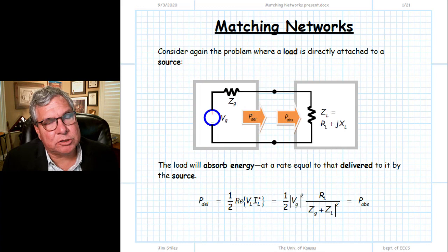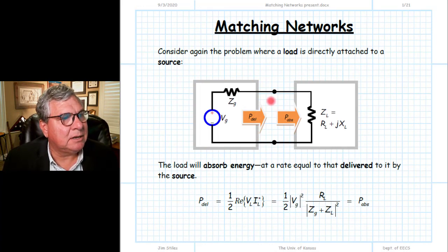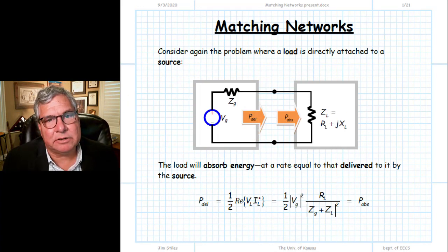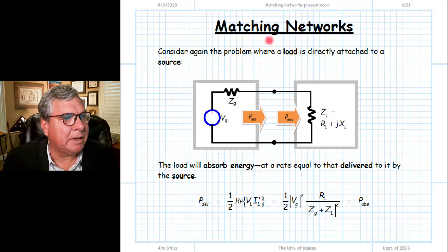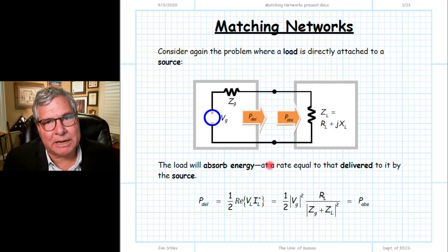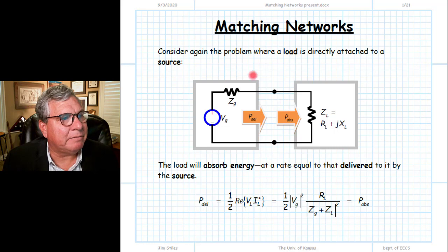So again, we return to our equivalent circuits. We have a long string of devices and energy is flowing from left to right. And we're going to define a port plane somewhere along that stream. Everything to the left we're going to replace as an equivalent source, and everything to the right has a load whose impedance is equal to the input impedance of everything to the right.